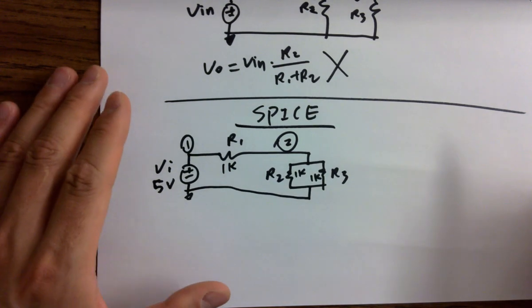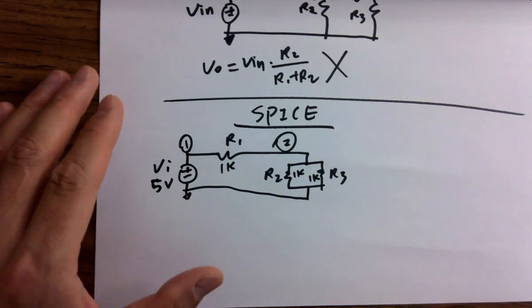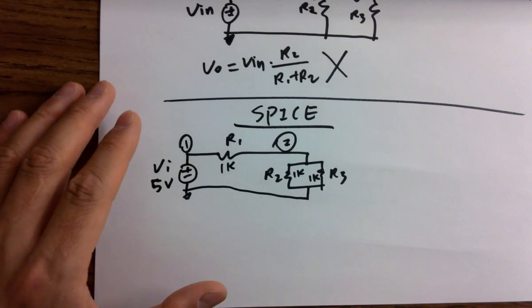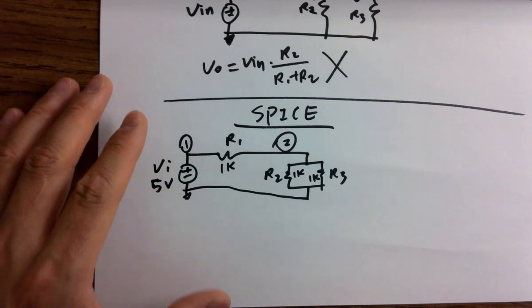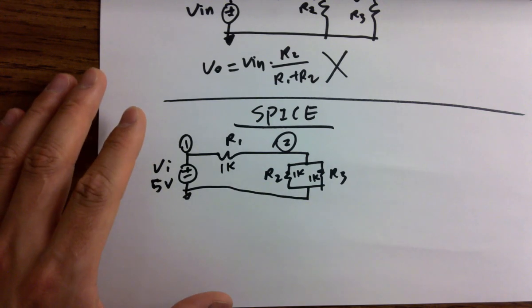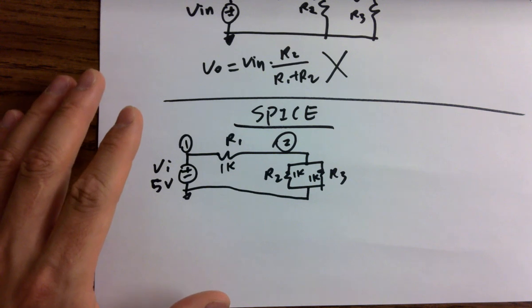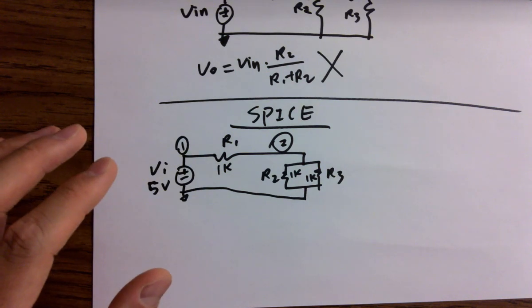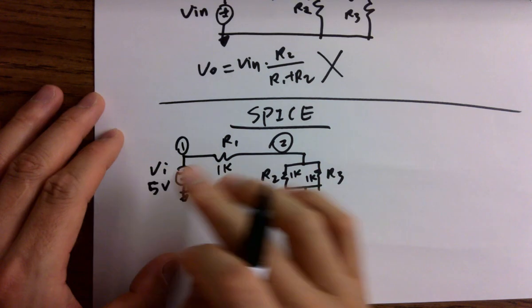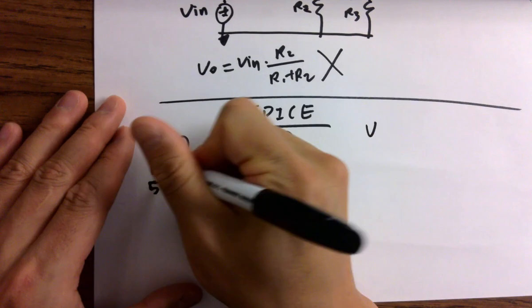And keep in mind in SPICE, when you start each line of the SPICE code, if you name the component as starting with V, it's getting recognized as voltage. If you put R in front of it, it's getting recognized as a resistor. If you put C in front of it, it's a capacitor. If you put an L in front of it, it's being recognized as what? Inductor, yes. Great. So now we can name it, but it doesn't matter what the letters are following that first letter. It could be VI, V Durango, anything, as long as it starts with V in SPICE. So let's call it V1, it's better.